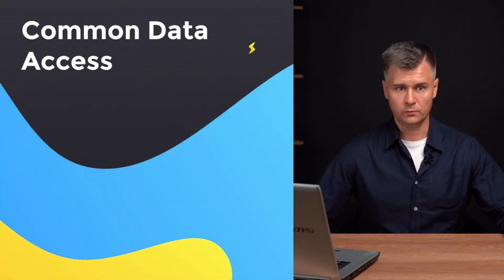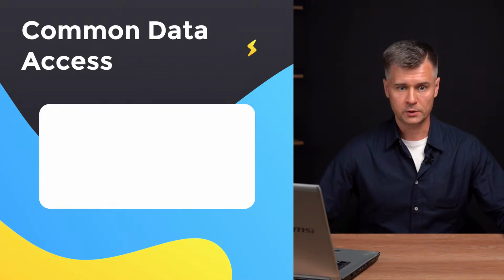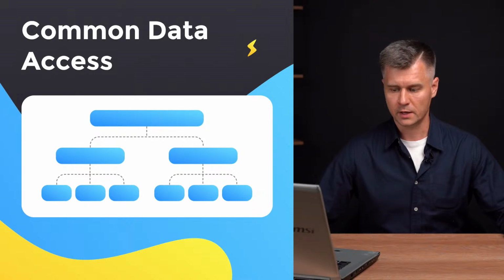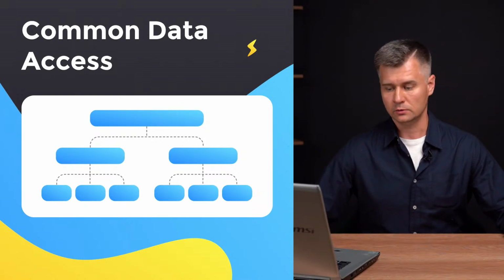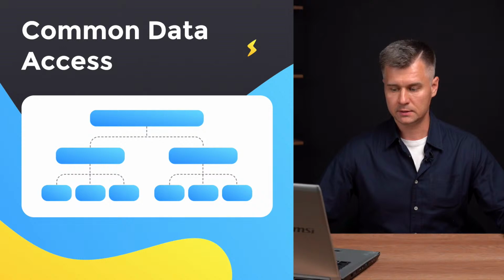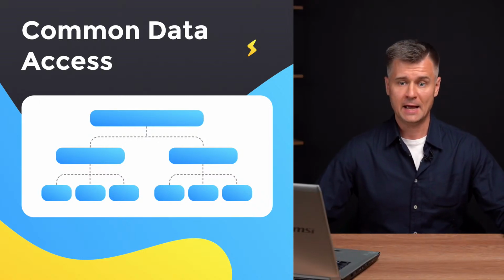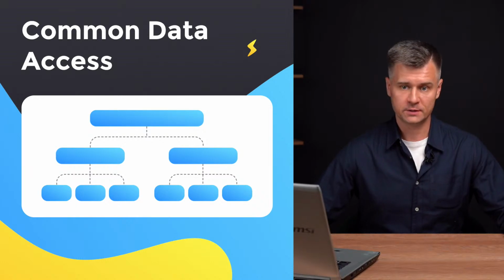Now let's move on, and one more option to mention is the Common Data Access. Most likely you are also familiar with the Common Data Access in ODA, but just a reminder: it is an API used to access structural information and object properties of imported models. It provides a way to do it in a simplified and universal form. So it's quite important when you work, for instance, with multiple formats and need a unified procedure to access the data.